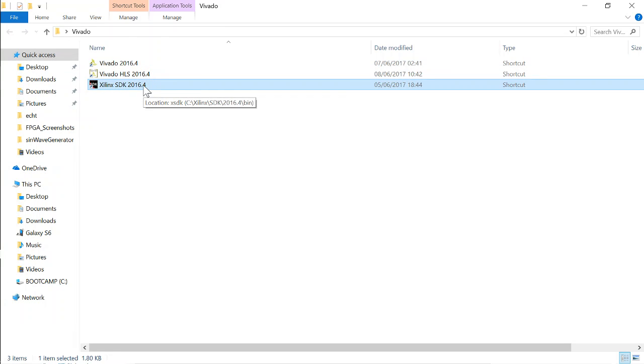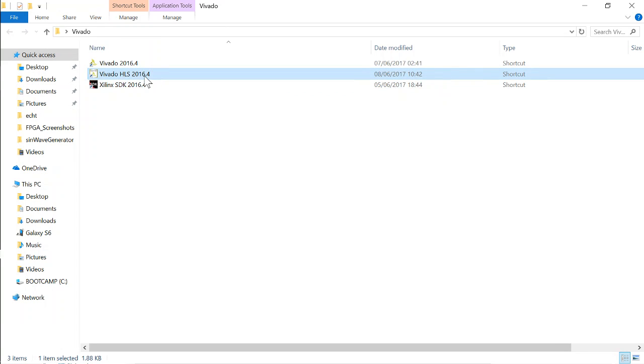So in this Xilinx SDK environment, what you can do is that you can program the ARM processor using two USB to micro USB cables, and effectively you can see the result in a serial terminal of your choice, like PuTTY, and you can save it into a text file. It's all in CSV, so it allows easy further processing in Excel or any software package of your choice. So let's start by having a look at Vivado HLS.